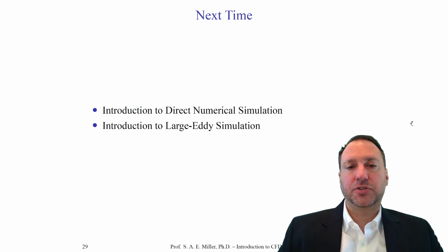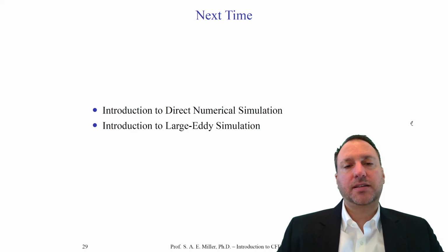The second set is a new kind of turbulence model, which has become very popular in the last 2 decades. Of course, it's called large eddy simulation. The objective is to resolve and simulate through temporal integration the largest scales of turbulence and model through turbulence modeling the smallest scales. Next class, we'll talk about both these approaches and look at some examples.